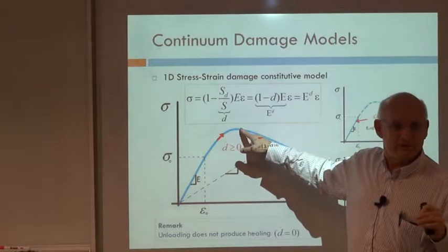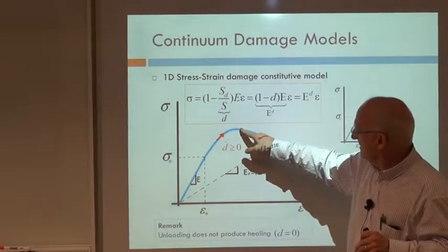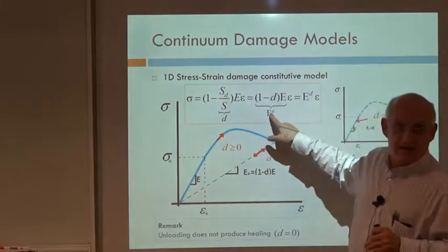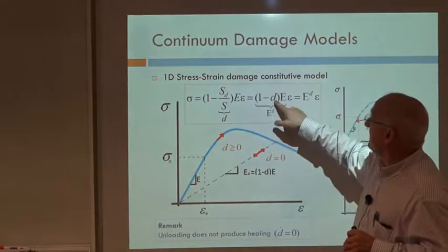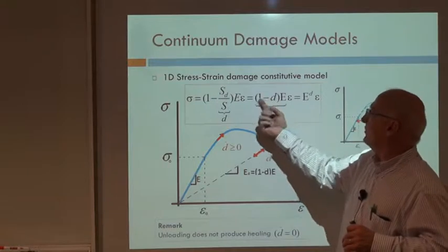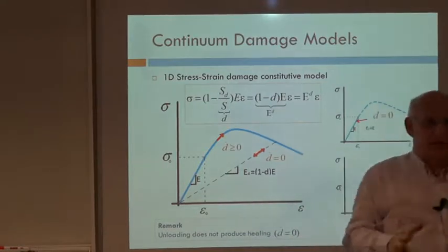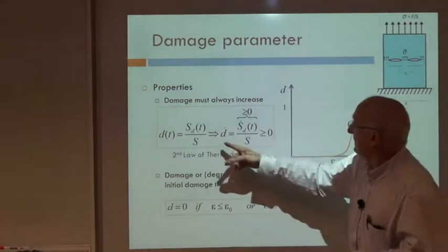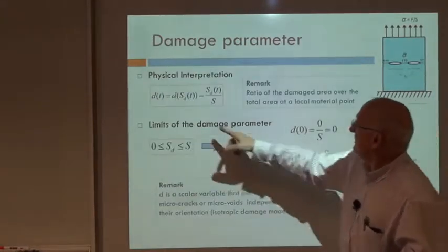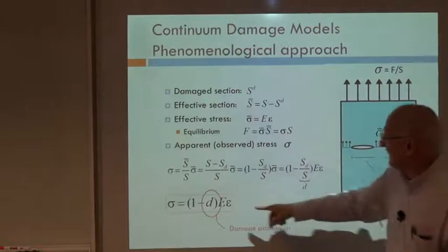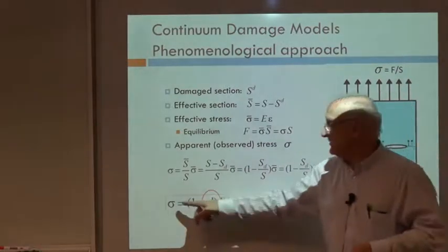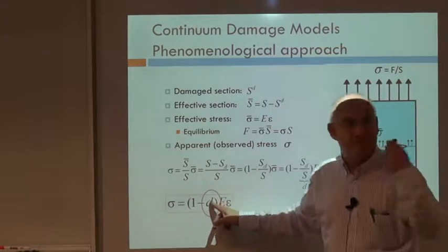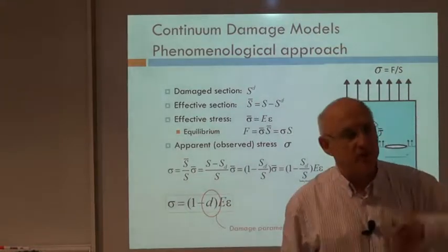I mean the other line that is straight, the ED. Well, ED is not linear. I mean, this is part of the model. The factor 1 minus d just comes from the approach I've taken. So that approach says that finally the fundamental equation that I'm going to impose is sigma equal 1 minus d times E times epsilon. No minus d squared or minus d to the logarithmic.